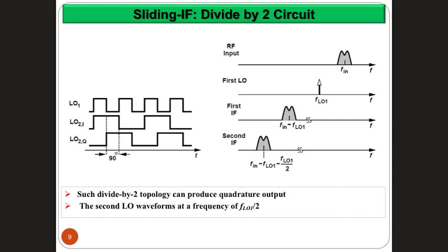The first bit counter is 1 0 1 0 1 0. The second bit counter is going to be 1 and it stays for 2 of these, and then 0 stays for 2 of these, and so on. The third bit changes every 8 of these, and so on. So this is how you implement those frequency dividers, by simply counting.